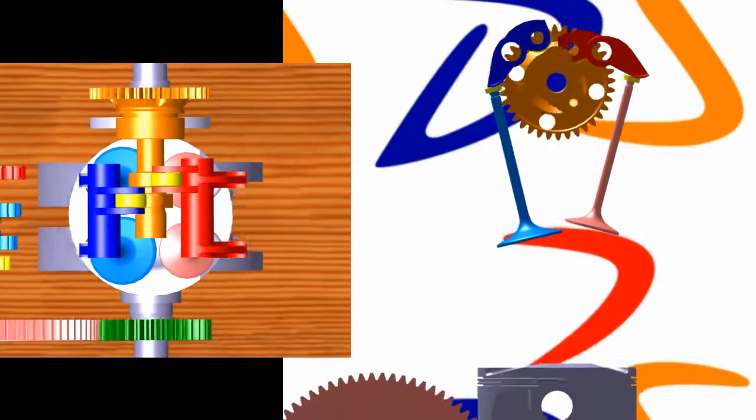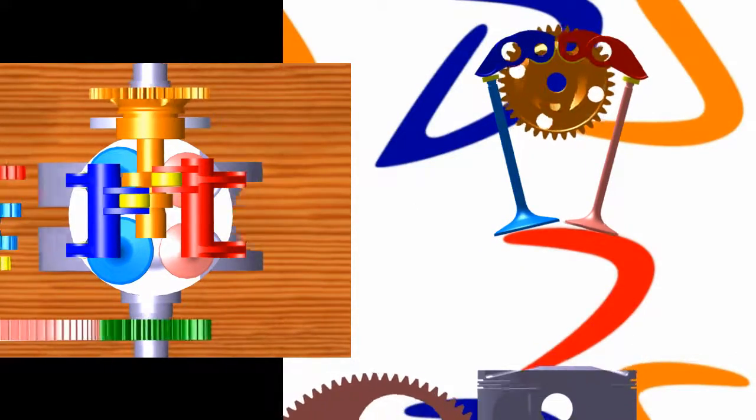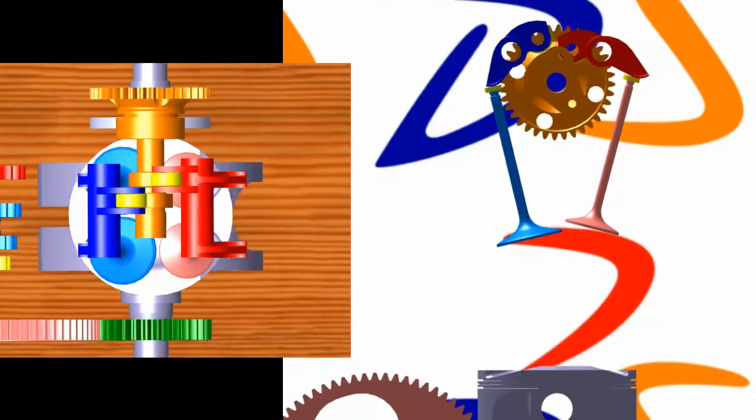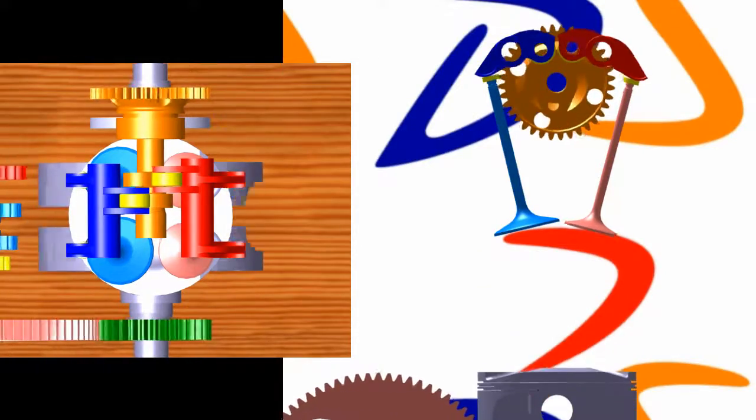Now looking at the valve assembly, the camshaft is the primary driver for this sub-assembly and is driven off the crankshaft through a gear ratio using 2 revolutes. The rockers are fixed in place using revolutes and actuate the valves through a combination of a curvature roller joint between the rollers and the cam lobes and a surface contact between the rocker arms and valves.